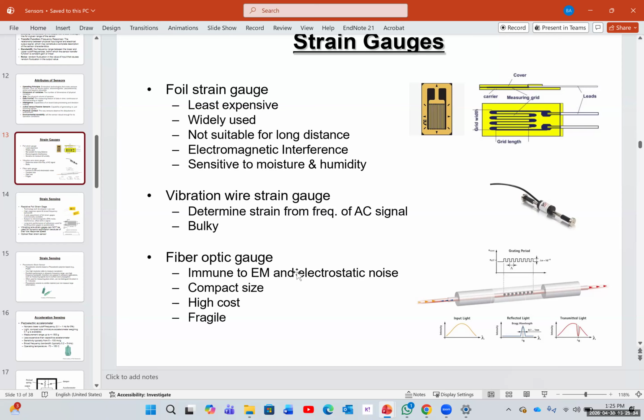This is the reason we use modulation. If you don't use modulation and you just want to send voice signal, the length of your antenna would be around 1 mile, roughly 1 mile. That's the reason we go very high frequency. We use modulation. In modulation, you have a carrier frequency. So this is a different topic. It's from signal systems and communication systems, but I'm just going to briefly mention it.